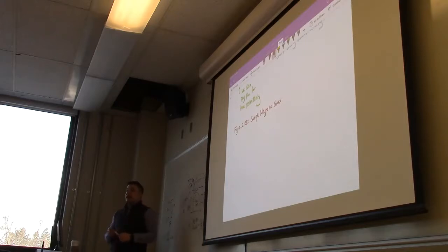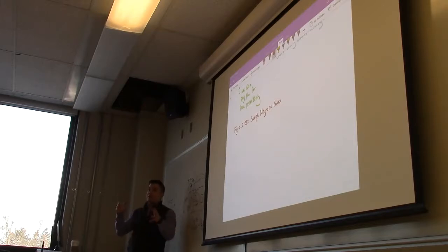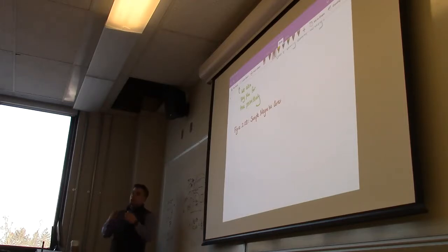The way you calculate the leakage inductance would be different because the permittivity of the path is the same for both. You're still going to have a leakage inductance. So the leakage inductance is not, in any case that I know of, ever the one doing the work for you, right? So even for the motor, it's the magnetizing inductance that's conducting the energy from the rotor to the stator or vice versa.